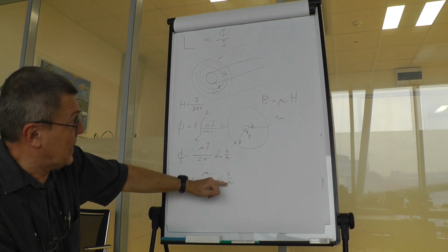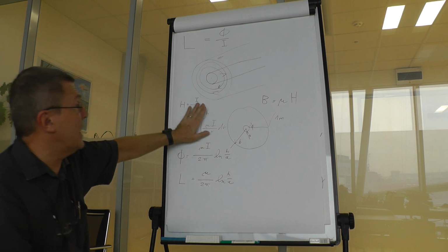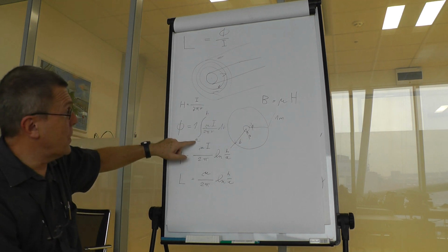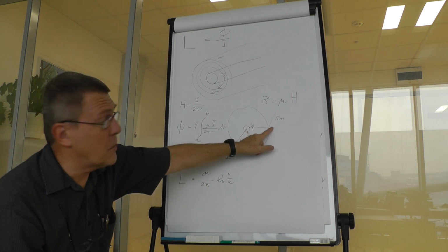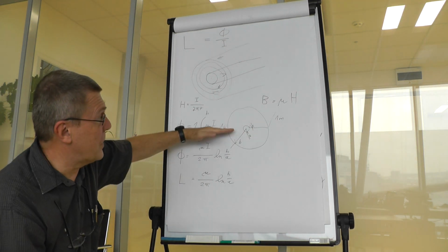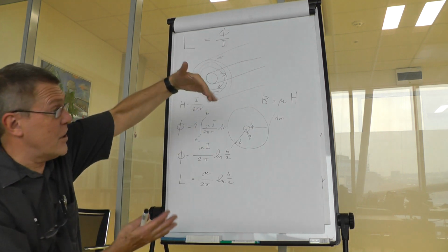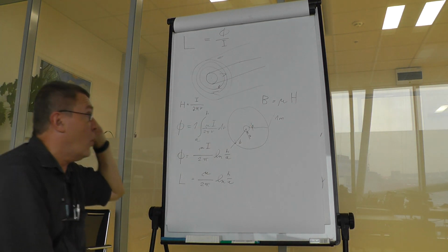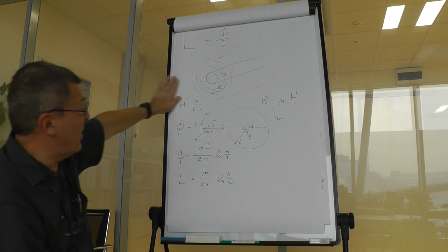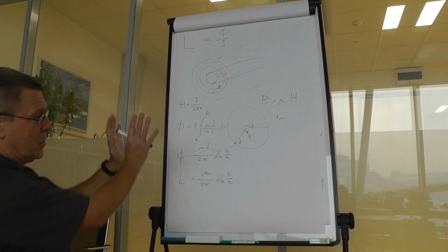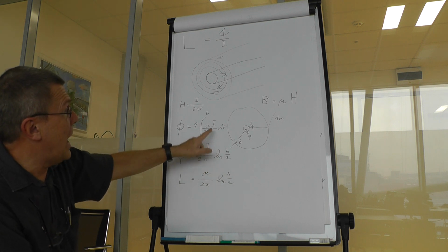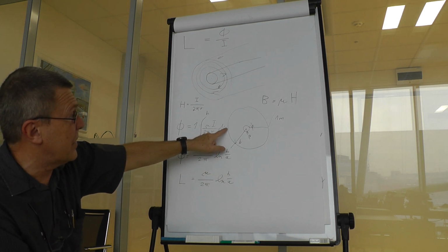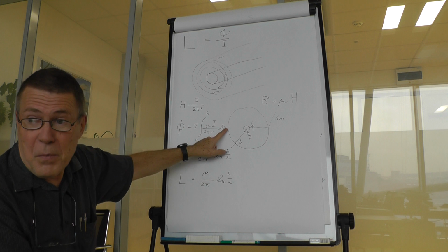How has that happened? Well, first we had the integral, which was from A to B, from inner conductor to outer conductor. We have been integrating through the whole path to catch all the magnetic field. Now, after carrying out the integration, we had some constants and we had a logarithm of r, because the integration variable was r.